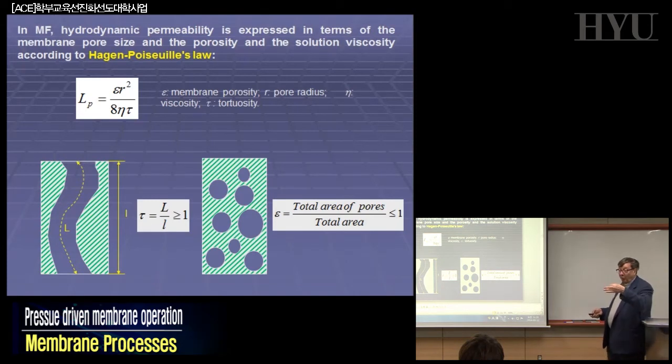If you have only one pore and all the rest is blocked, membrane surface porosity is very low. So we have to realize membranes with a very open membrane surface, which is the best, most interesting. But if you do this, you will learn you lose the mechanical properties. And our membranes have to work under pressure for 10, 15 years, not for a few hours in the lab. So you have to be able to find a system with good mechanical properties and useful membrane surface.